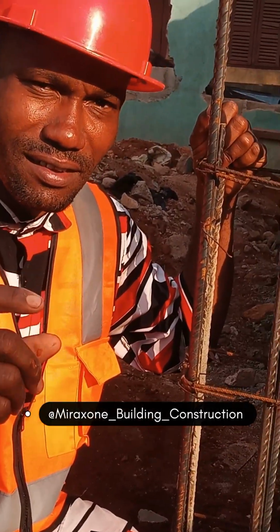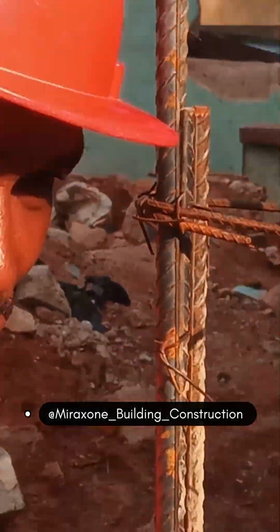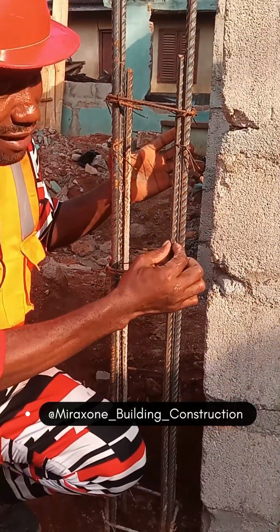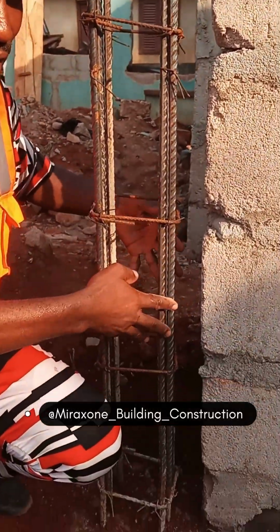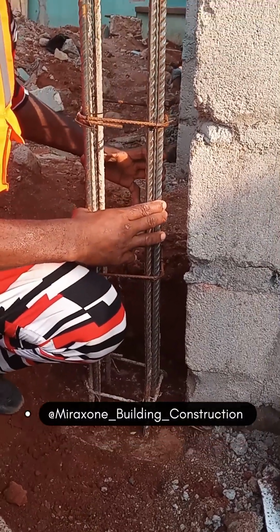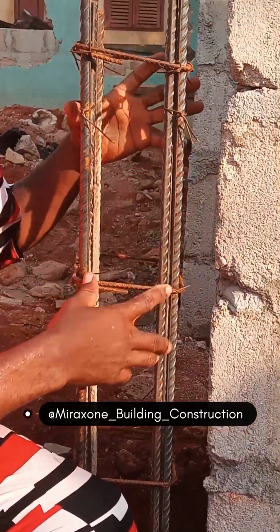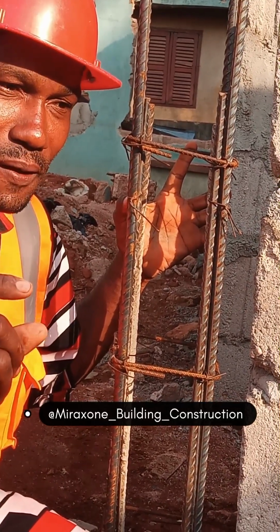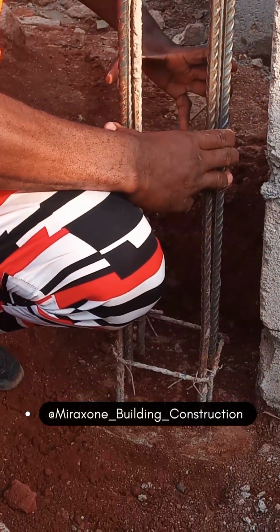So we are going to use this column as a case study with regard to the lapping length we have been discussing, okay? I want you to watch how this column has been placed. This continuous column has been placed in such a way that it enclosed the starter bar, okay? Come closer. Look at the continuous column. Look at the starter bar from the foundation. You see how the continuous column has enclosed the starter bar, okay? But some other amateurs used to do it in such a way that the starter bar is outside, enclosing the continuous column. No, don't try it. It's an error in construction, okay? You will have to do it in such a way that the continuous column encloses the starter bar.